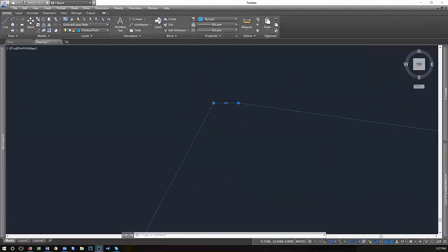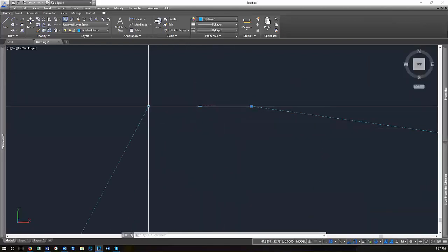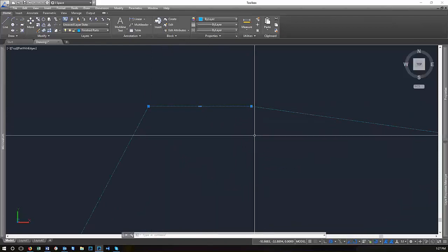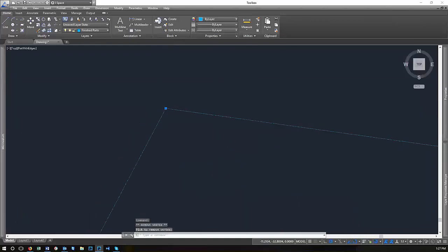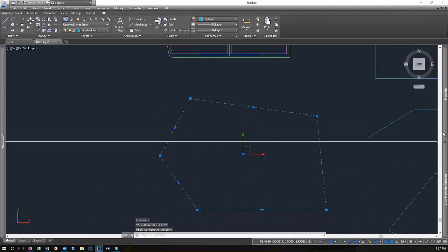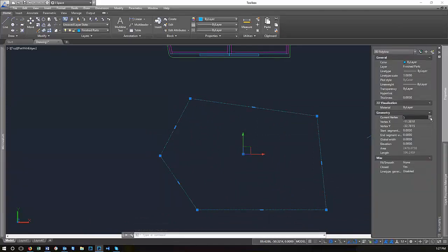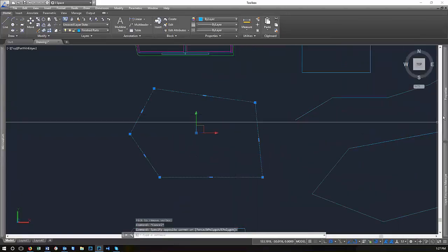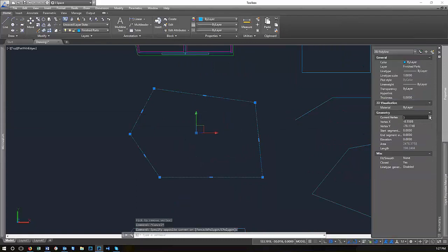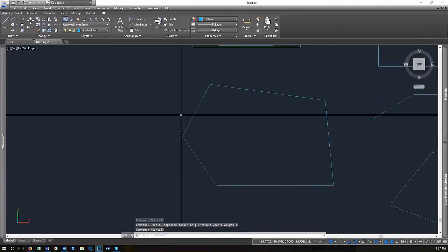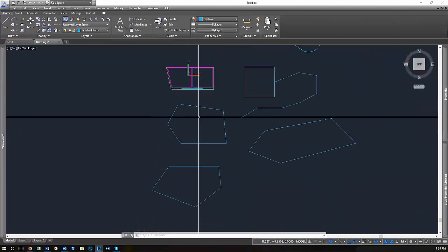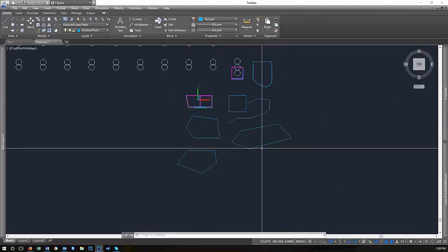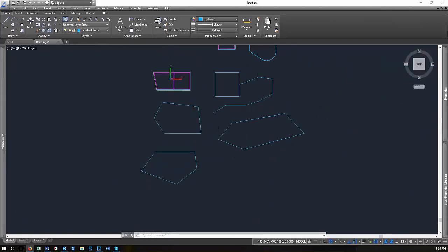and now it draws them off of each other. So now you can see 1 and 6 and the line that's connecting them. And then if you want to eliminate that, you just hover over it and remove vertex. Now I have only 5 points and current vertex 1, current vertex 5. That's where they are. It's not showing it. I don't know why the indicator went away, but it was there, and the 5 points all the way around and the start point ends up back at the start point. Very good. Okay. All right, so grips.